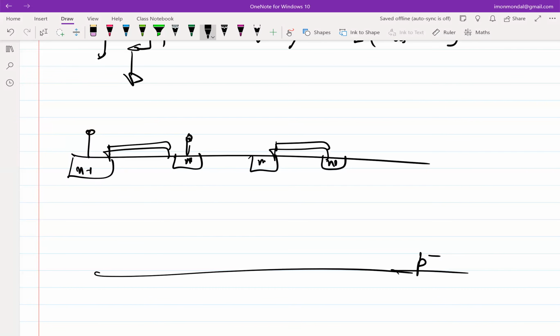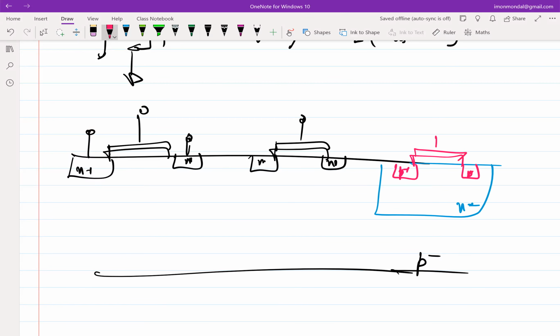And your PMOS transistors will also be on the same well, but because a PMOS requires a separate body, right? It requires an N-type body. So generally we give it an N-type tub, and then you have P plus, and this is what you do. And if you want another PMOS transistor, you can give it a separate tub. So PMOS transistors in general can have their own body, but NMOS transistors in principle don't.